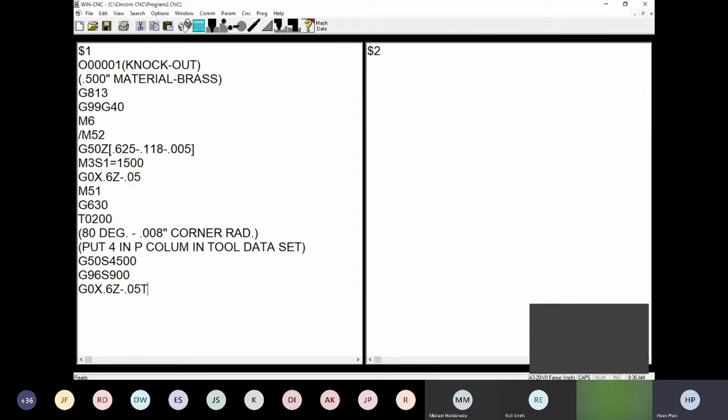And then also right here, we can turn on the offset. As you pay attention right here, I always call the tool with no offset. The reason is that for some tools, like those numbered above 31, we cannot call the offset together with calling the tool. If you command T3131 right here, the machine will not allow you to do this.